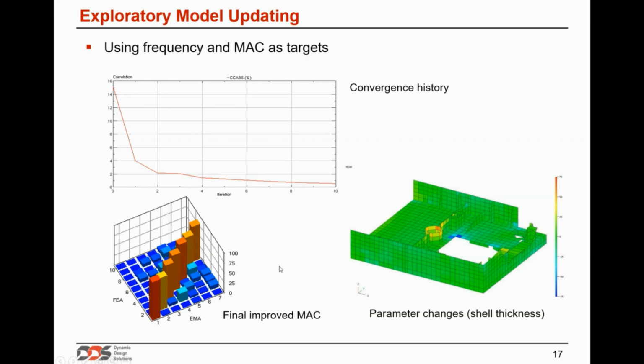So if you do not know what change is needed, then exploratory model updating element by element is like error localization or damage localization in a structure, because using a software like FemTools that can support element by element updating using thousands or 10,000 parameters is no problem, then you can create this kind of graphic visualization of the areas that need a change in stiffness or mass.